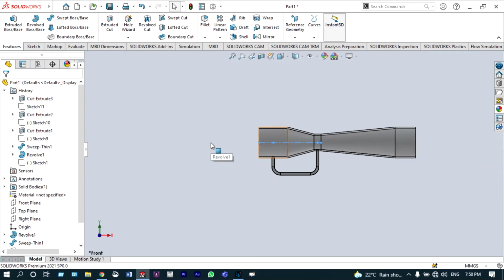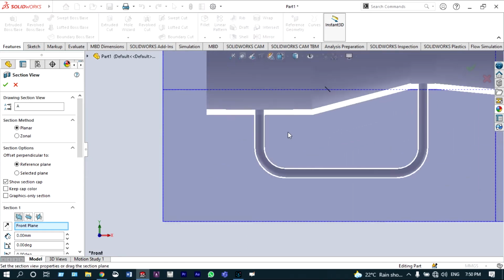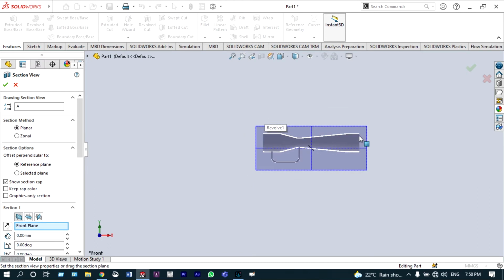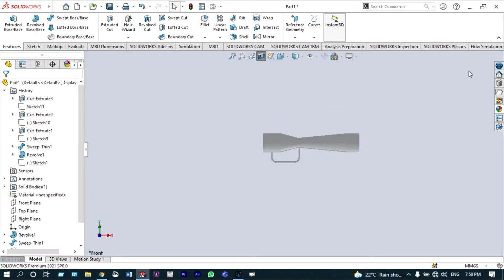Now you can see this model from front view. You can cut it and see the segmented view of this model from front view. So it is showing perfect. Our model is ready for simulation, right? Next to that, we have to provide some kind of leads at the entry and exit location, because we want to have one closed volume for this CFD simulation or CFD analysis.